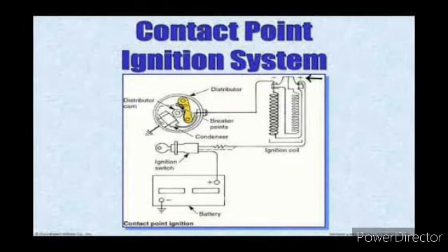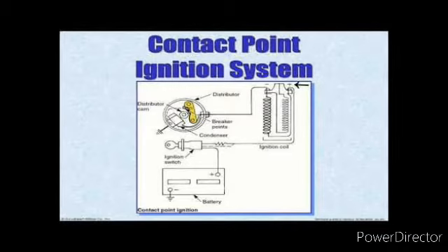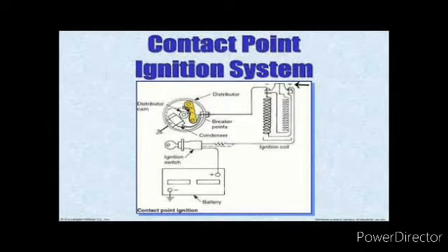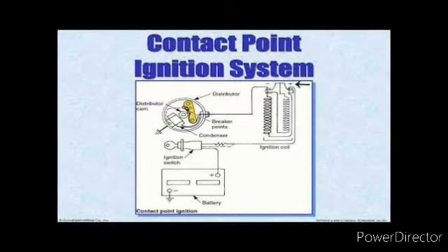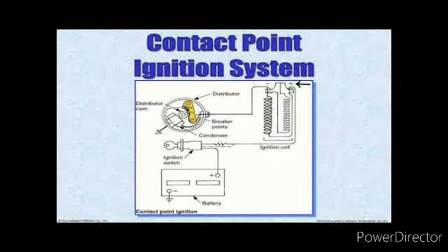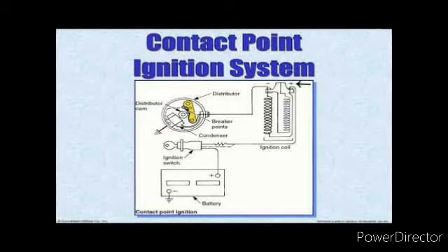However, if the point dwell is too great, the contact points will not open far enough, resulting in arcing or burning the points. This may sound a little confusing, but it makes sense when you understand that the points act to open and close the ground circuit. Remember that the breaker points open and close as the distributor shaft rotates. One half of the point set is fixed and the other half pivots, and there is a rubbing block on the movable half of the point set.